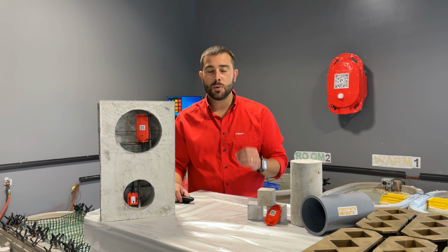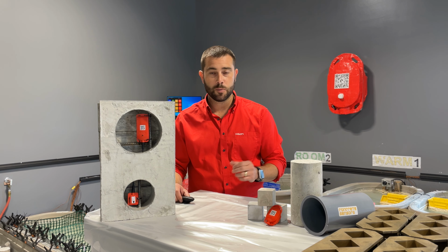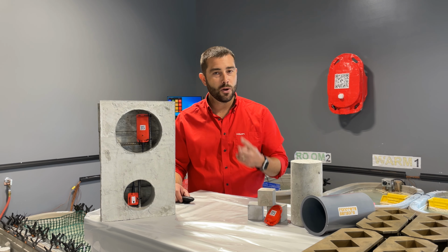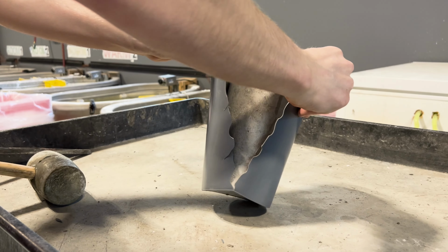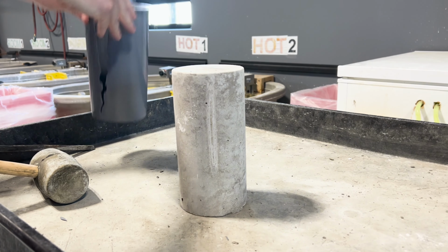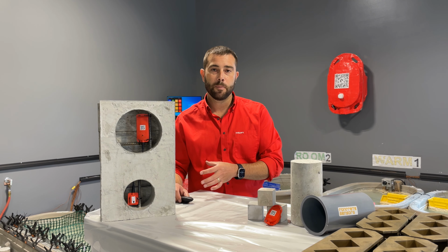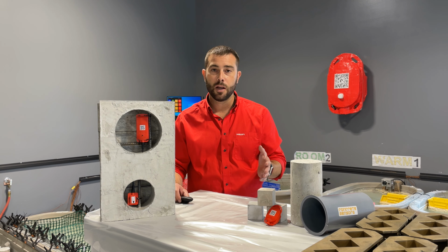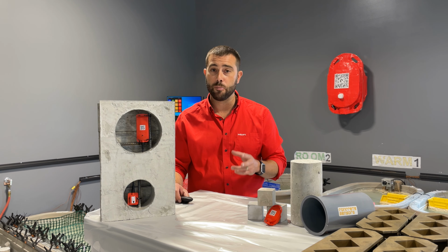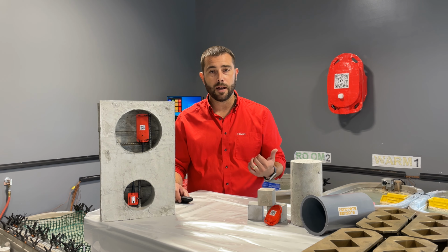Step 2, a little bit of homework here. You're going to need to establish a strength reference curve specific to your concrete mix. Now you have 2 options here. Your first option is to use existing data from a third-party testing agency. You'll take the break data and you'll enter it into our app. If you don't have that, that's okay. Your second option, and in my opinion, your best option, is to partner with our lab.